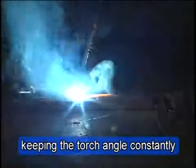When the large welding amperage is induced onto a small wire diameter, as in the case of CO2 arc welding, the arc force is generated in the direction the wire is being fed. This phenomenon is referred to as the arc stiffness. The arc force is stronger when the current density is higher. Furthermore, the torch angle affects the penetration and bead profile. Hence, it is very important to keep the torch angle constant when welding.